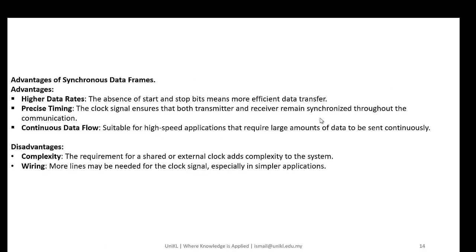Advantages of synchronous data frames: higher data rates, precise timing, continuous data flow. Disadvantages: complexity, of course, and more lines are needed, right? Because of the need to transfer the clock signal.